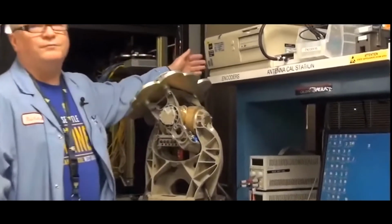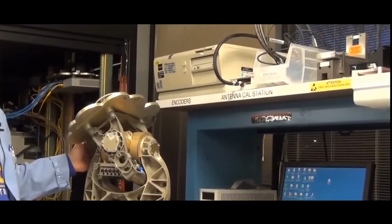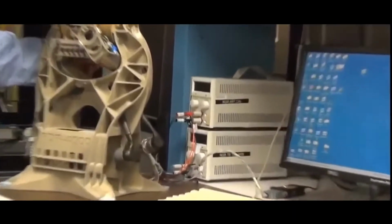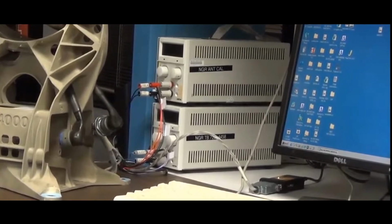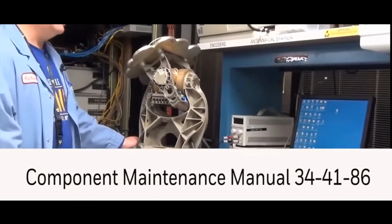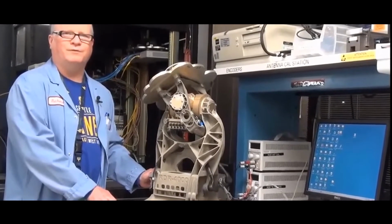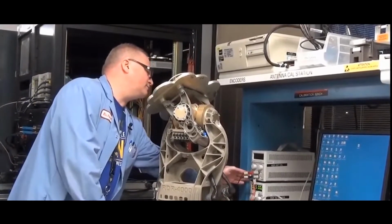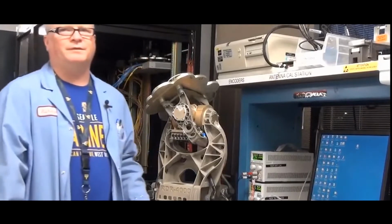We have a PC, it can be Windows NT or XP with calibration software loaded on it. Two power supplies, one for 6.5 volts, one for 28 volts, and a test communication cable. Part number can be located in the CMM. So step one, we're going to turn on our power supplies, 6.5 volt first and 28 volt second. Allow the power to come up.